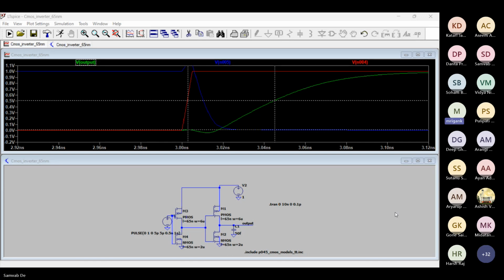Yes, it goes with the square. And if you go on reducing the voltage further, the transistors will enter the subthreshold region, where the current reduces exponentially. So although the total charge that you need to deposit is reducing, in the superthreshold region, as long as the gate voltage is greater than VT, VDD keeps the transistor in superthreshold. In that case, there is a square dependency, and as a result, the current is reducing faster.